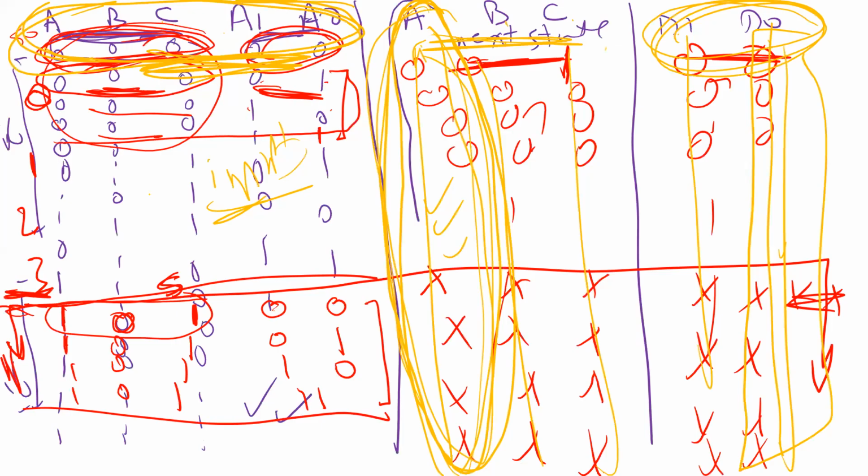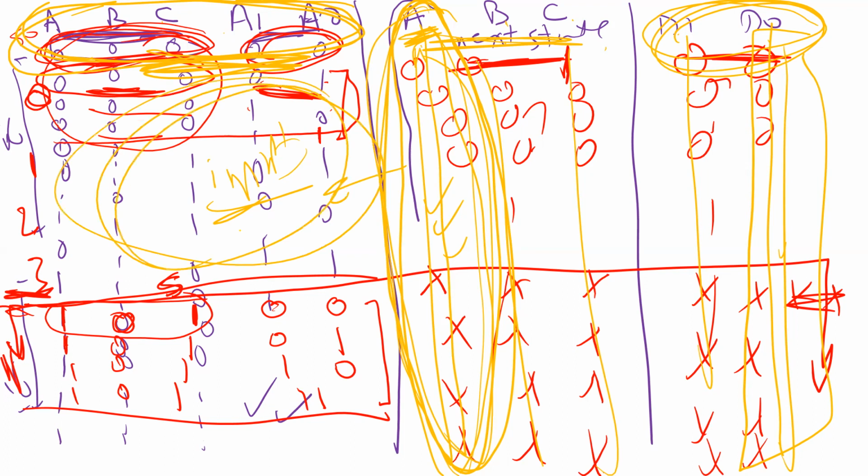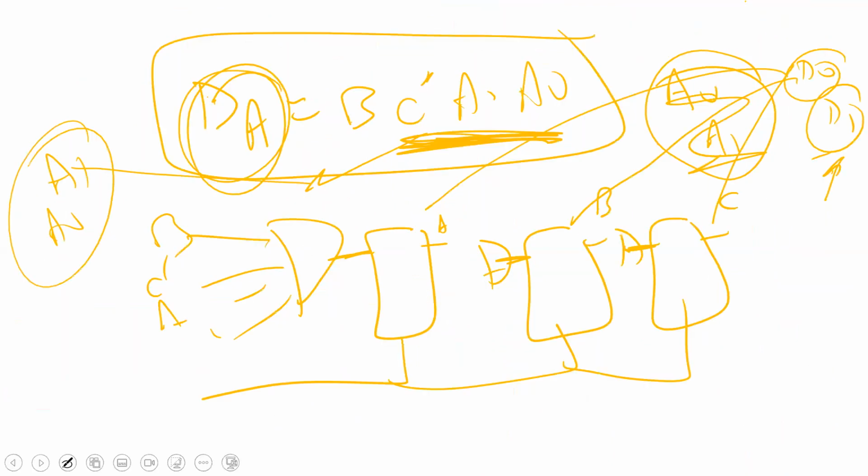Once you fill up this state table, you need to take this one, create this and simplify using the website or Digital, using these inputs. So these are the inputs here. Same thing, simplify this one. So this one should give you the input of flip-flop A. This should give you the input of flip-flop B, the input of flip-flop C. This should give you the output, and another output here. Okay, that's it. Once you do it, just run it in Digital or implement it.